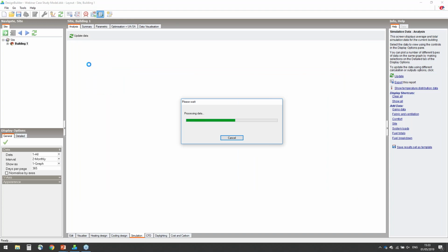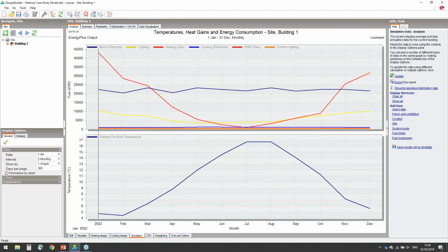DesignBuilder Simulation Manager allows us to run and control multiple parallel simulations and access the results. The Simulation Manager stores the simulation results. The results can be accessed in any compatible model at any other time. It is a convenient way to store, access, and compare simulation results either via Results Viewer or by loading results into the DesignBuilder main application. Using Simulation Manager, simulations can be run on a local machine, local network, or the cloud.